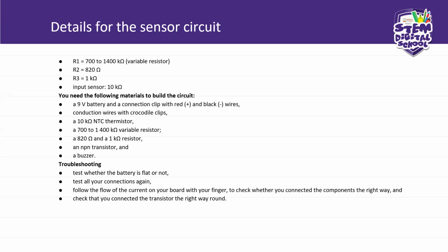You must be careful when you get those thermistors. Remember, there's a PTC, positive temperature coefficient, and the NTC, the negative temperature coefficient. You buy the NTC, you get the NTC, not the PTC. The PTC is for the fridge.